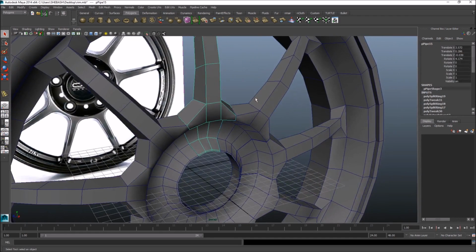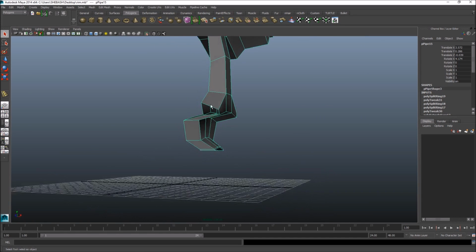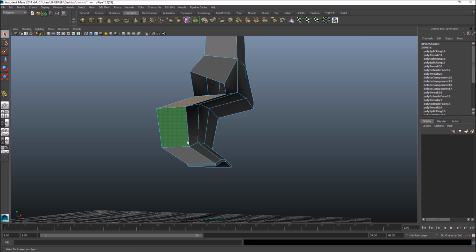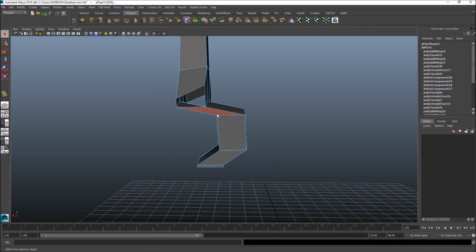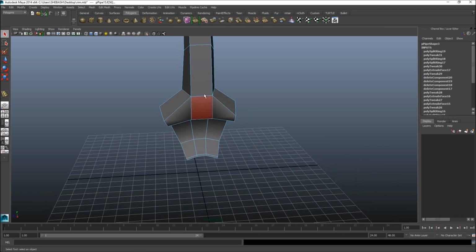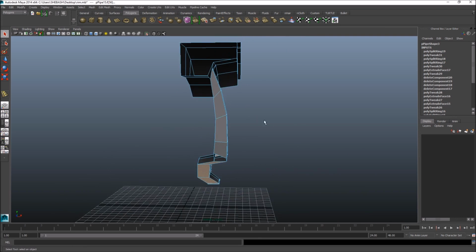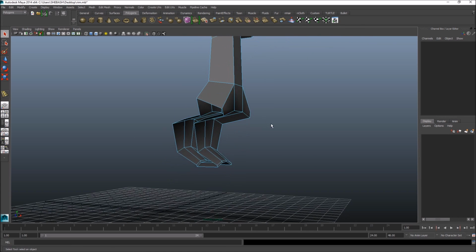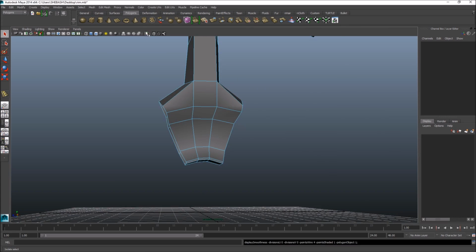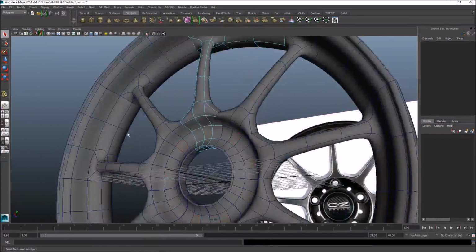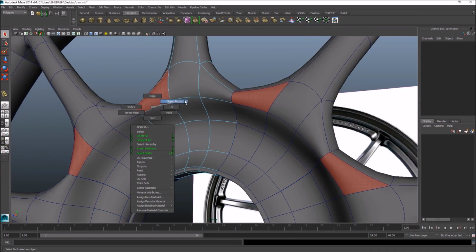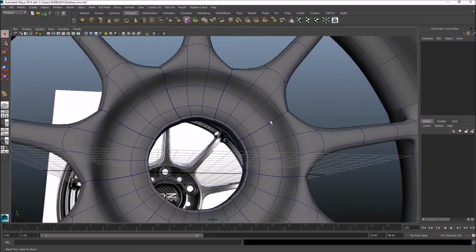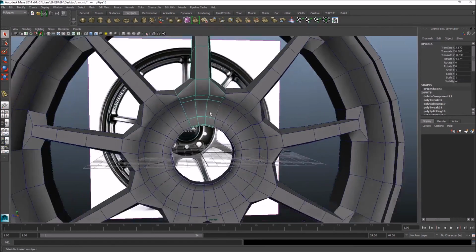And now what I want to do is I'm gonna grab this spoke, and when you extrude faces, it creates obviously these side faces, but we do not want them, because when we join this spoke with the others, it's gonna create some problems if I don't delete them. So let's just get rid of them. Yep, that's better. So now we can check the smooth version with the 3 key. Yeah, I mean, it's taking a good shape so far.